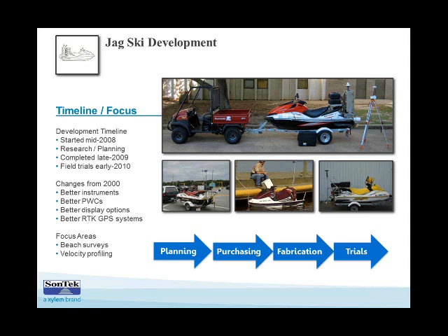HydroSurveyor offers an interpolation feature that allows the user to develop some options about the interpolation spacing and the area to interpolate. It's all very easy to use. It's basically point and click. You don't have to do any coding or programming or anything like that. And we found the interpolation to actually work really well, both for bathymetry and for the velocity.